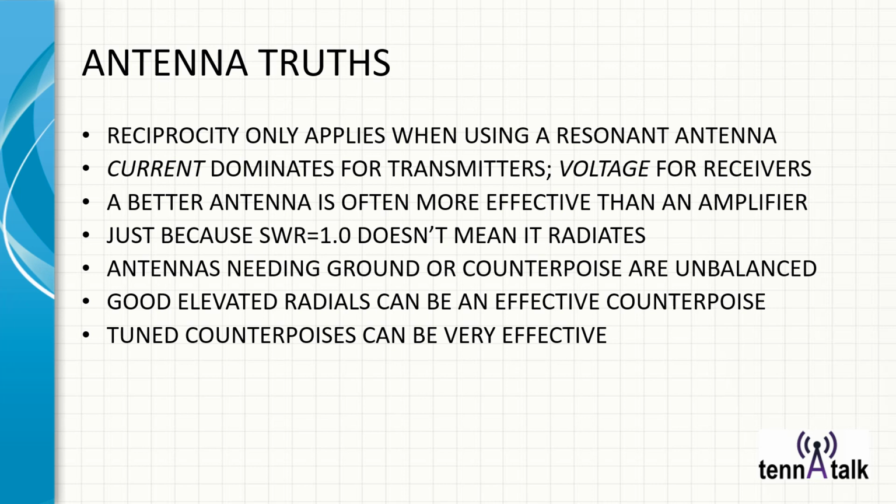You can peak it out that way, and then you can peak it out by maximizing the current into the counterpoise separately from tuning the antenna vertical whip portion. And in fact, MFJ offers what's called an artificial ground with 2 separate sections, a tuner for the antenna radiator and a tuner for the counterpoise. And it can be very effective if you're operating verticals.